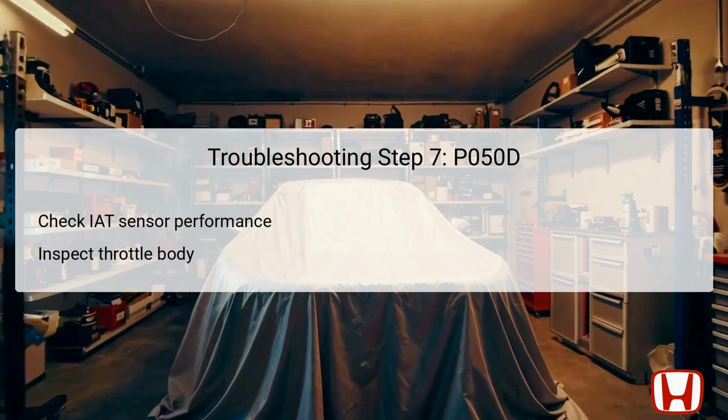If the IAT sensor appears functional, check for possible obstructions, dirt, or carbon buildup in the throttle body. Cleaning or addressing any damage can drastically improve cold start conditions. It is essential to wrap up the process by ensuring all involved components are functioning accurately.